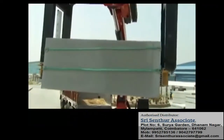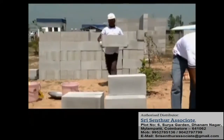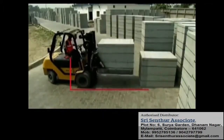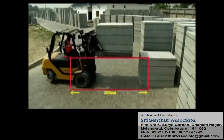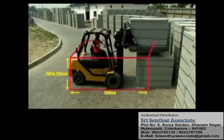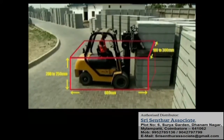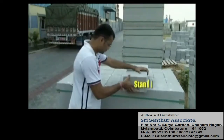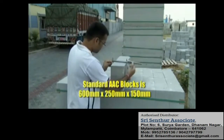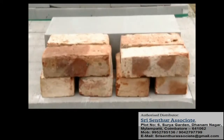AAC blocks are a new age green building material that is easy to handle compared to clay bricks. Though larger in dimension, the blocks are light and come in various sizes, which vary from 600 mm in length, by 200 or 250 mm in height, and by 100 to 300 mm in thickness. A standard concrete AAC block of 600 mm by 250 mm by 150 mm is equivalent to about 8 clay bricks.